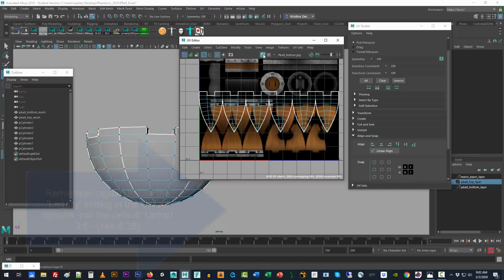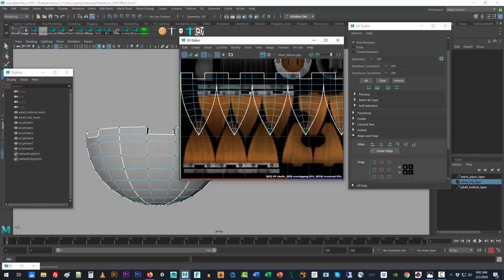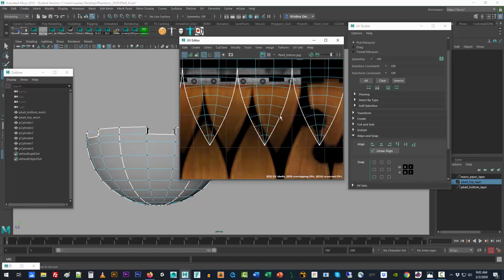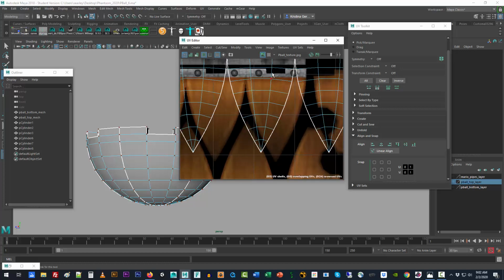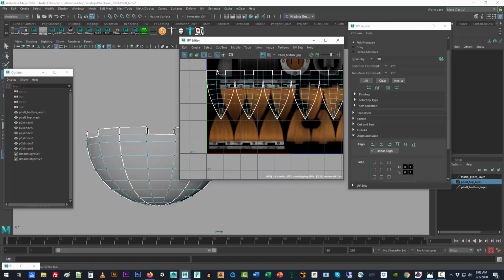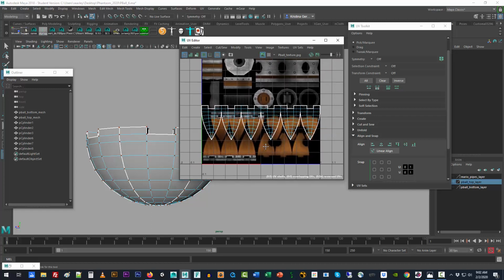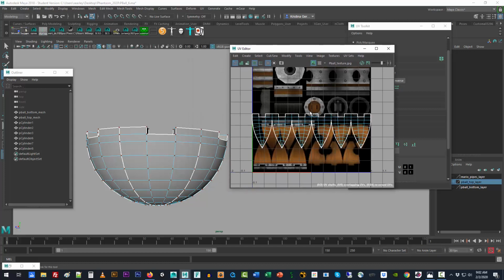And again, we can just turn on the picture. Now we're kind of getting closer to what we need to line things up. Not just these orange slice wedges here, but if we look at the texture for the Merlons, they're actually lined up. Everyone starts high, goes low with a little divot, comes up again. So that's a good thing to do, is just be aware of the malleability of doing these UV sets and what you can and can't do, which is slightly different from modeling.